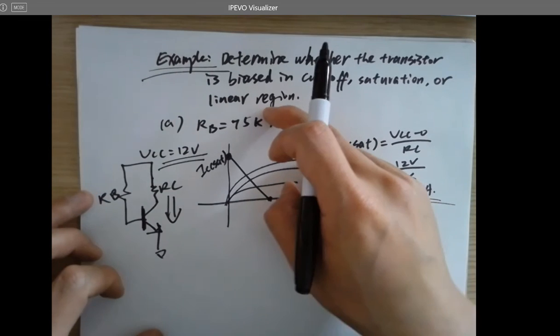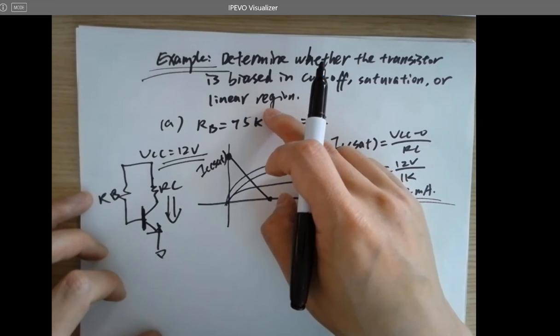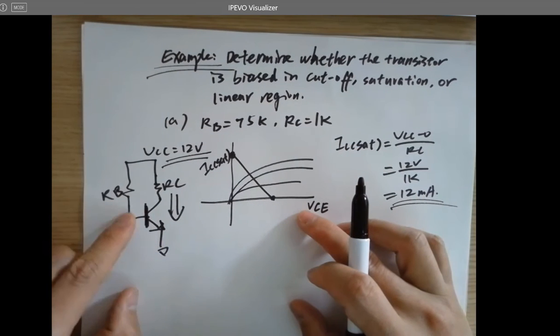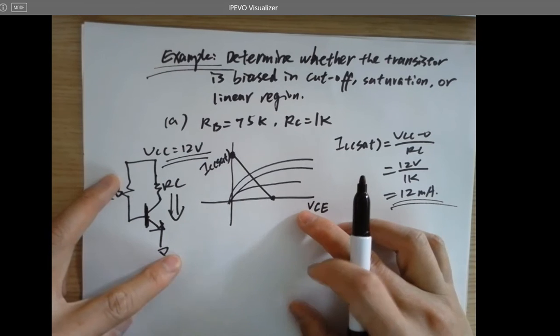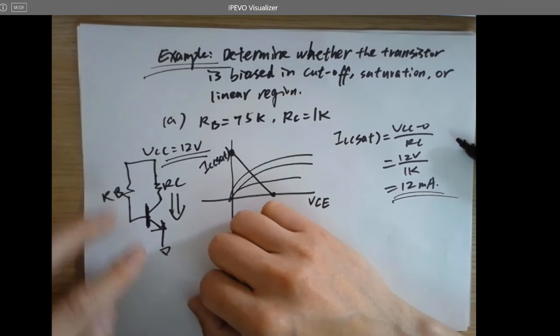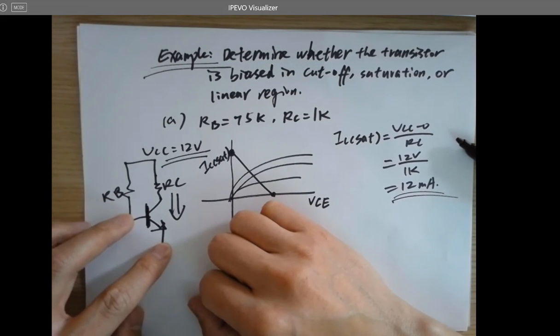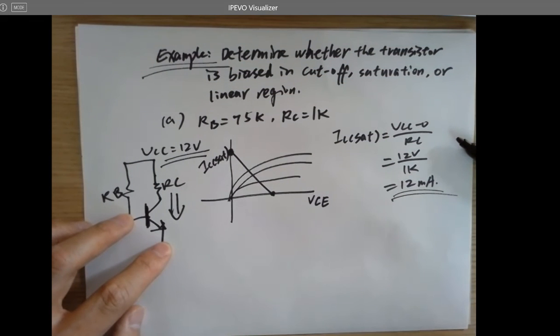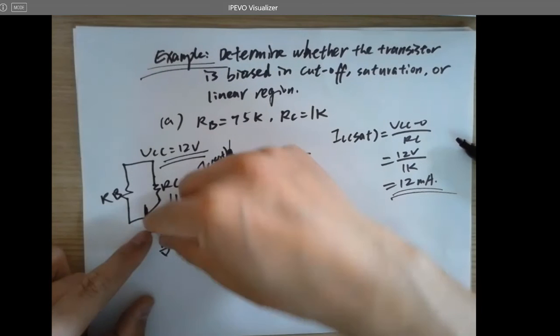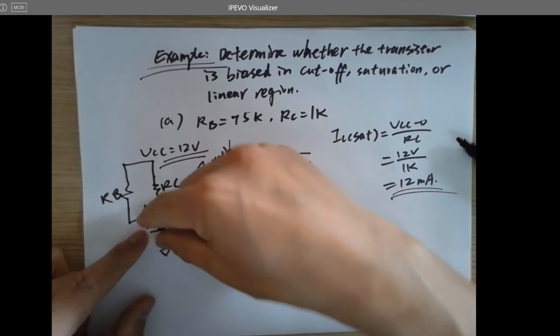You're asking why it's not in the cutoff region. Because 12 volts is way higher than 0.7 volts. Before it's being turned on, there's no current. The 12 volts will be totally dropped across this guy, just for a very short moment. So it's going to turn on this PN junction. The PN junction at the bottom is NPN, so the PN junction will be turned on.